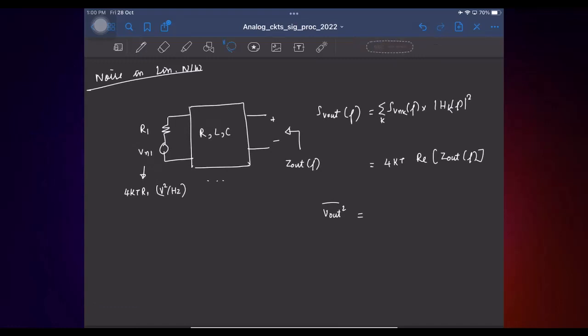And we saw what mean square noise is, and what was it? If again it had only RLC, how can you quickly tell what is the mean square noise? kT times E0 minus E infinity. What is E0 and E infinity? Initial and final energies. Basically I have to, I mean, where should I apply?